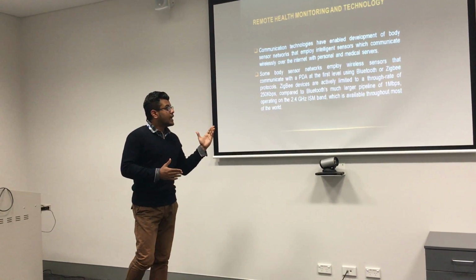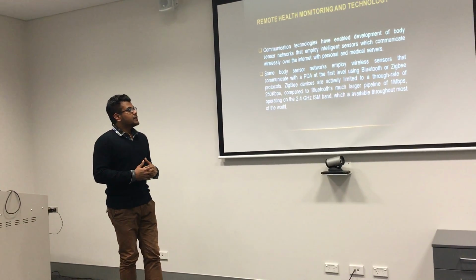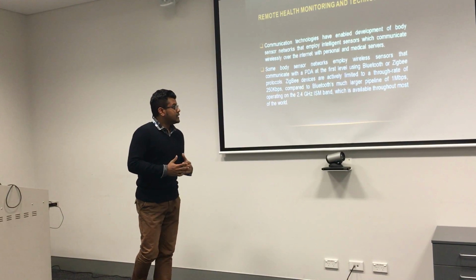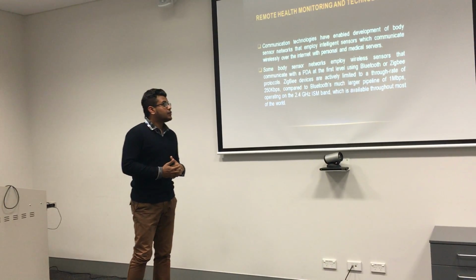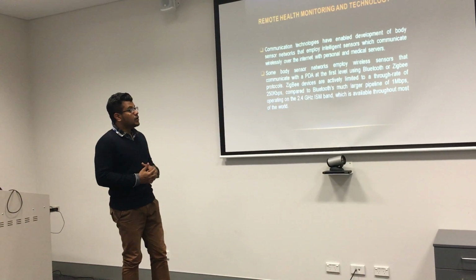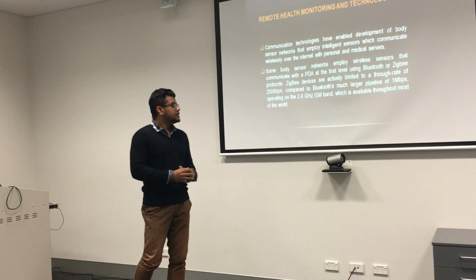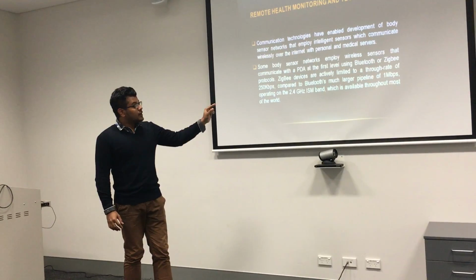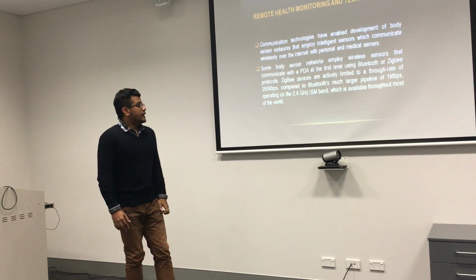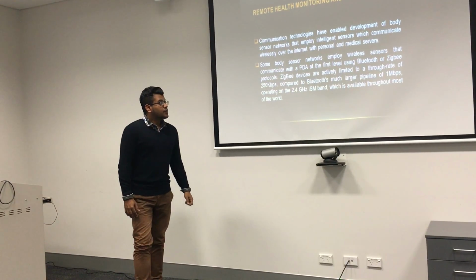ZigBee devices are limited to a throughput rate of 250 kilobits per second compared to Bluetooth's much larger pipeline of 1 megabit per second, operating on the 2.4 gigahertz ISM band. I repeat, it is the 2.4 gigahertz ISM band, which is available throughout most of the world.